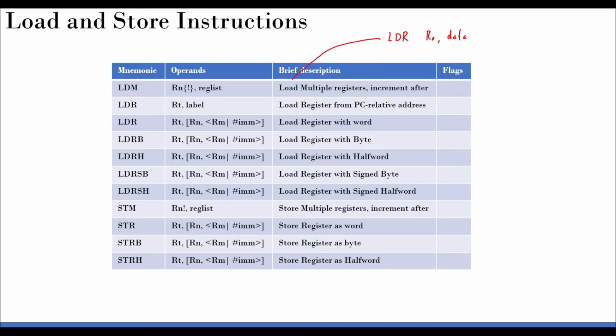So this statement corresponds to this. Then what I can do is something like LDR R1, and then something like this. This bracket has a meaning. It means I'm not interested in loading the content of R0 into R1, but rather the content at the address in R0. R0, for example, has the address of this memory location. So when I have this bracket, whatever is the content of that address location will be loaded to R1. Let me put some example to prove that point.